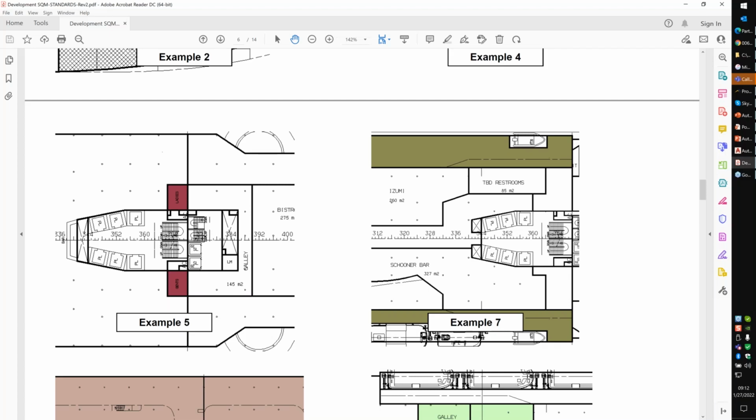If you exceed that, you may double click on a drawing and it's going to open up AutoCAD and tell you the drawing's not valid, or it just opens you up to a blank drawing. One of the things you have to be careful of is you want to minimize the number of steps it takes in a folder structure to get down to where you want. You want to keep the names as small as possible, but still functional.